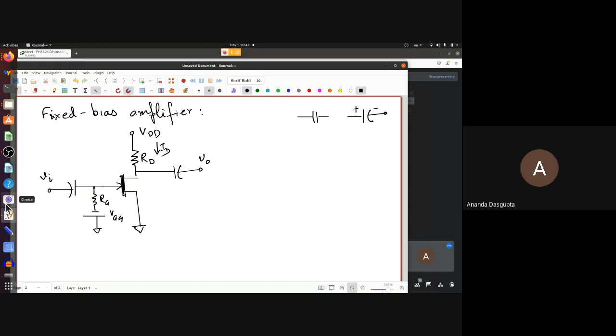And then when you do superposition in any circuit, you have multiple sources. You are supposed to calculate one source at a time. Take one source, calculate the voltages and currents due to that. Then take another source, calculate voltages and currents everywhere due to that. And then add up corresponding voltages and corresponding currents, once you're done with working it out for every source.